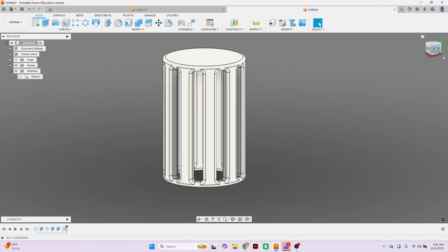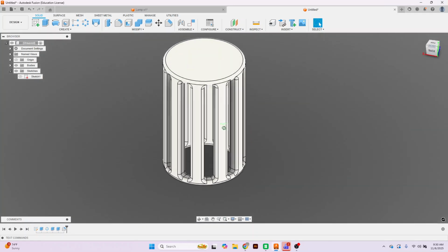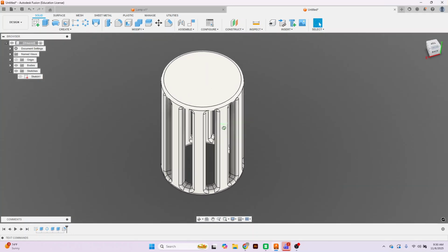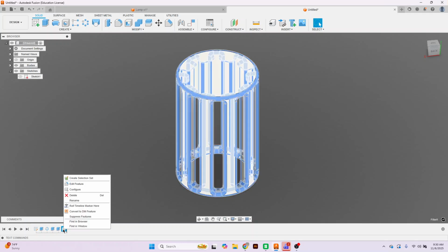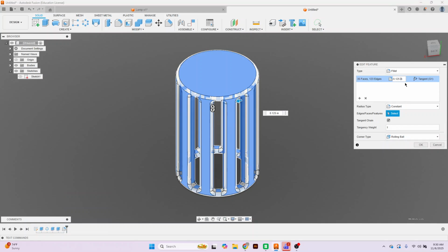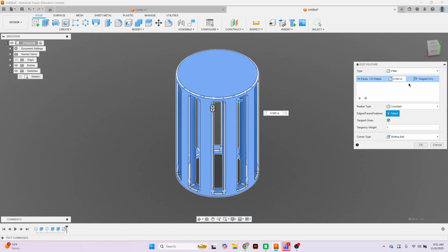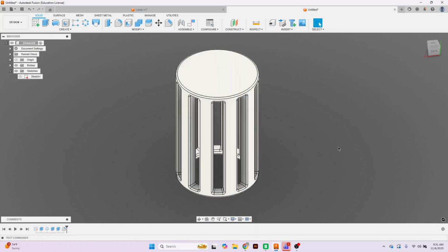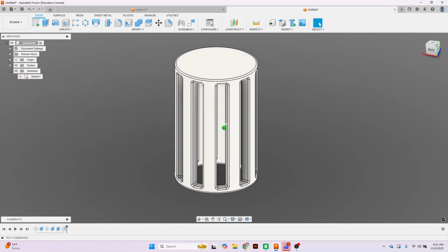Now what that did is that made a fillet on every single curve of that feature. You could also go back, if you made a mistake, you can go and edit that. And if you wanted to change it to something lower, like 0.065, you could do that as well. It's your part. You could decide how you want to do it. Whatever you think looks good.